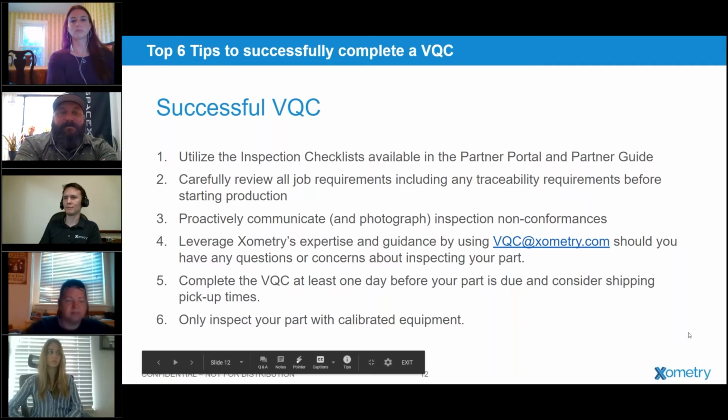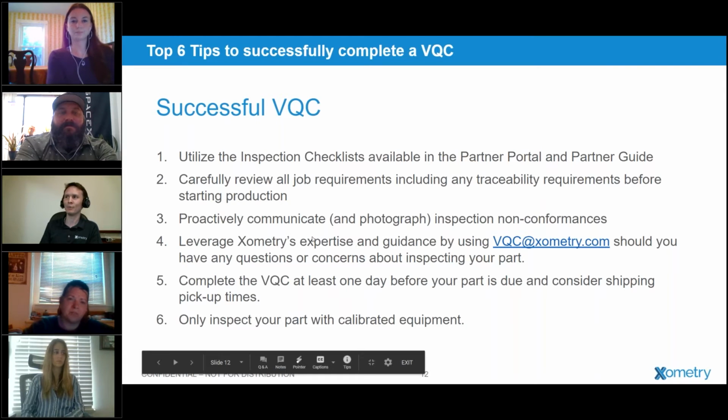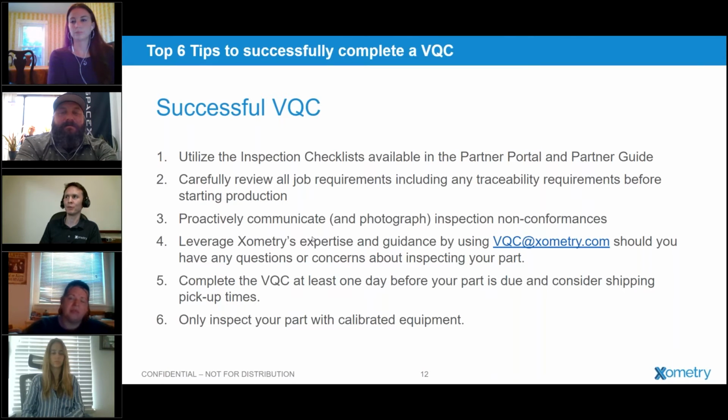Yeah, I was going to say, I think if you're manufacturing, it's like a rite of passage to be burned by realizing you need a material cert after you're ready to ship the part, because it is so much tougher to get one afterwards, but so easy to ask for one when you're purchasing the material. And the best time to check is when you get the material from your supplier, right? A receiving inspection on your material can save you thousands and thousands of dollars. It's huge. So again, reach out to us if you have any questions or concerns.